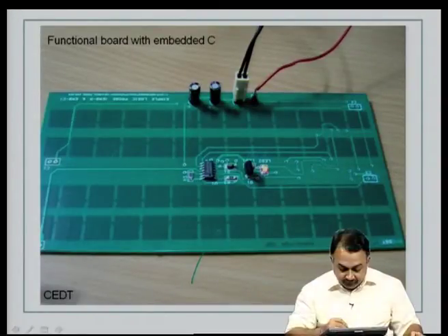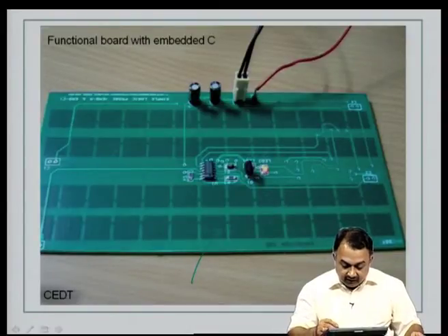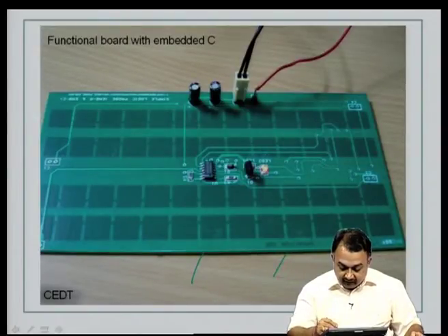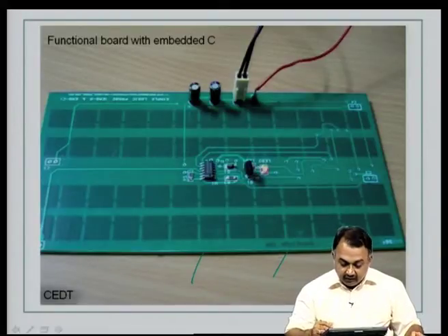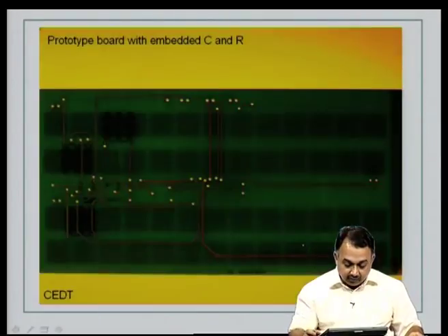You can see here the inner layers, that is capacitor, and this is basically a small circuitry demonstrating the working of these embedded capacitors. Now, the idea is from this picture, if you are using a high end, manufacturable industry design, the geometries of these capacitors have to be reduced to such an extent that you can reduce the real estate of the entire board.